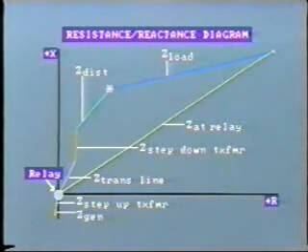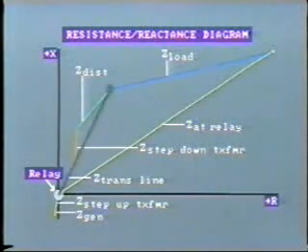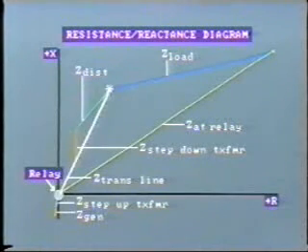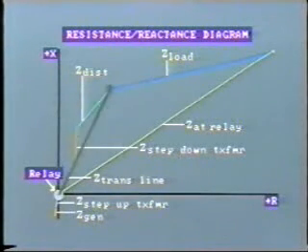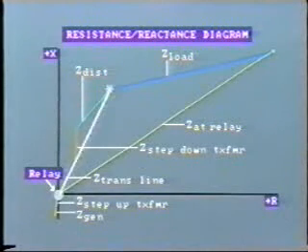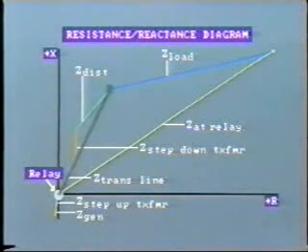If we have a short circuit close to the load, you can see that there will be a dramatic decrease in impedance, but its phase angle will increase considerably. As the fault becomes closer to the source, the impedance is much less. Consequently, the fault current will be much higher.